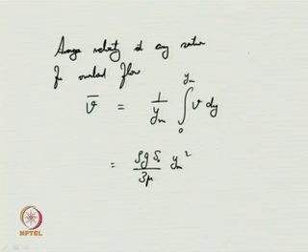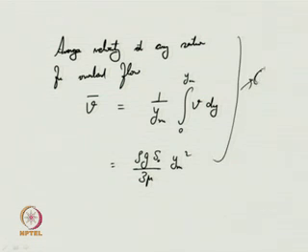So, these portions we have referred from the text by Ven Te Chow on open channel hydraulics. So, this average overland flow velocity is computed in this way. This is as good as your uniform flow, meaning this velocity is the same as the uniform flow.